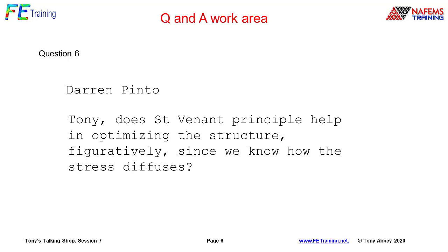So there, yes, I often use St. Venant's principle in the sense that if I can see a high stress region and I can't get rid of it, I might turn that into a region of the design space which is not going to be changed, and just accept that high stress which is sitting there, knowing that I can come back and do something more subtle with that local detail. So yes, that kind of plays a role. And that really comes down to, I think, Steve's point, which is basically we want to use engineering judgment here. We don't want to get one hotspot stress for some reason, from poor modeling or because we haven't set up the problem very well, and be driven by that hotspot stress in the optimization globally. Well, let's get rid of it.